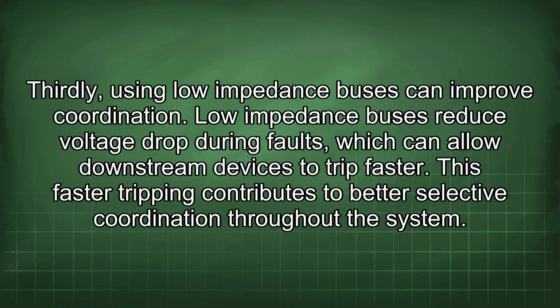Thirdly, using low impedance buses can improve coordination. Low impedance buses reduce voltage drop during faults, which can allow downstream devices to trip faster. This faster tripping contributes to better selective coordination throughout the system.